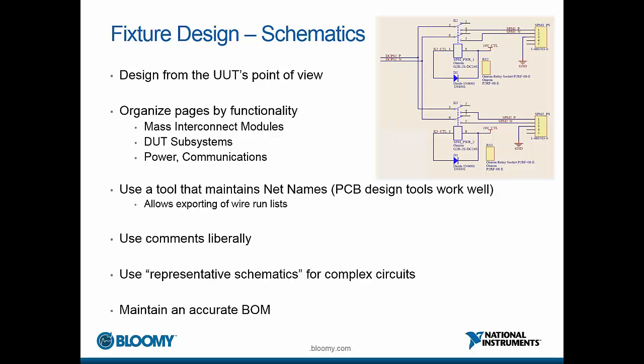Schematics are the preferred design approach because they provide a visual representation of the connections. This is most helpful when conveying your design to fellow engineers or management. Because the major purpose of the fixture is to test the UUT, schematics should be designed from the UUT's point of view. Sheet organization is especially important on larger fixture schematics. Organizing pages by functionality can greatly improve readability.